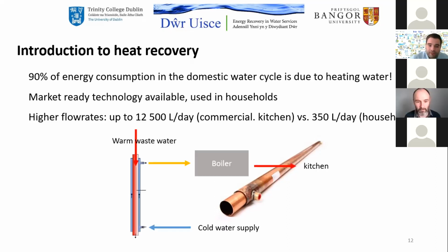So the idea is that the cold water supply coming in is preheated in the heat exchanger before it goes to the boiler, and thus it reduces the fuel consumption of the boiler. And so it's preheated using the warm wastewater going through the middle of our heat exchanger.